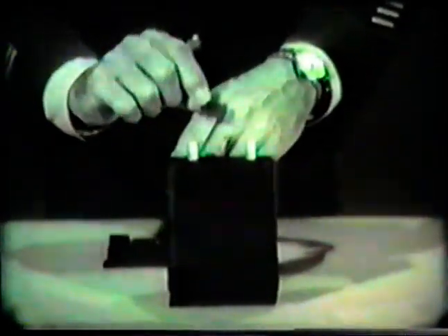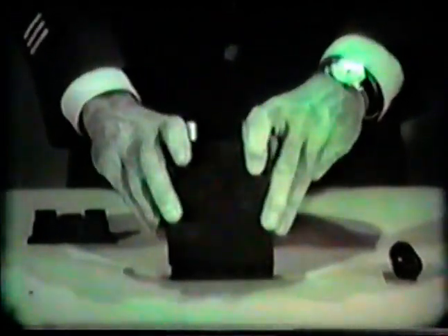Most aircraft batteries have a separator protector which is fitted across the top of the cell group to hold the separators firmly in place and protect them from vibration or servicing damage. The cell container is closed with a cell cover, which is sealed to the container with an acid-resistant compound. Holes in the cover permit the negative and positive terminal posts to extend out of the cell. At the center of the cover is a hole for the vent cap. The vent cap screws into threads in the cell cover.